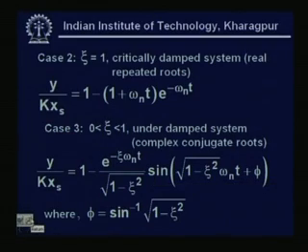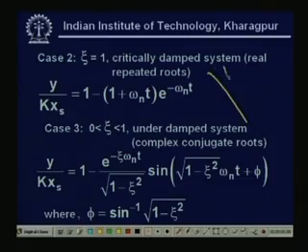Now, mostly we will try to bias our second order system as an underdamped system. If you look very carefully at analog meters, especially voltmeters, you will find that if you apply some voltage, the needle will go, make a slight overshoot, then come back to the original position.